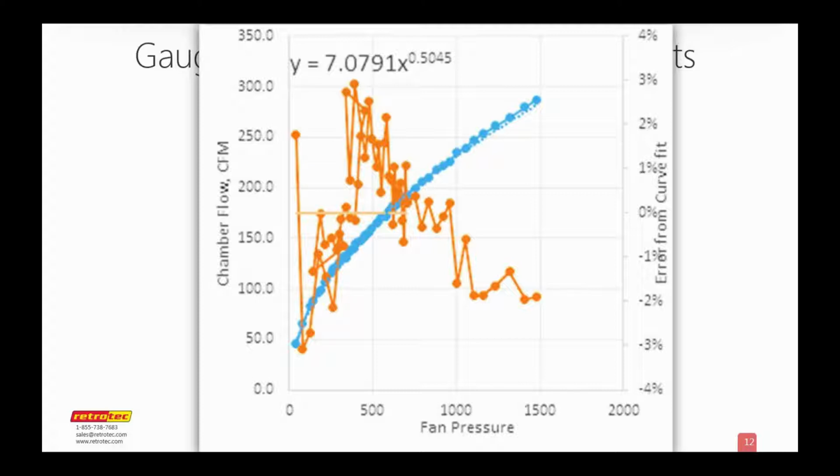And a great story I had once was a person was testing a commercial duct system, and they were using a duct blaster, which has an axial fan in it. It's great for testing residential ducts at 25 pascals, but it's not great at testing commercial ducts at high pressure. So he said, yes, I'm reading 850 CFM, and I'm reading 2 or 4 inches of water column. And I said, well, it's totally impossible. It's like you telling me that my old Toyota Tercel can go 280 miles an hour. It just can't. You just can't do it.